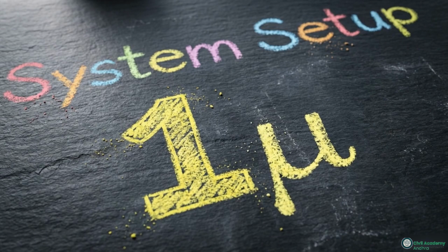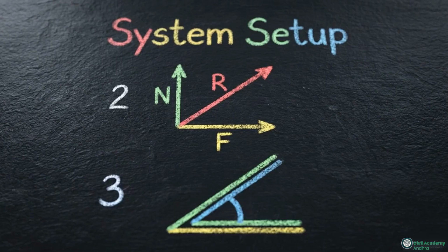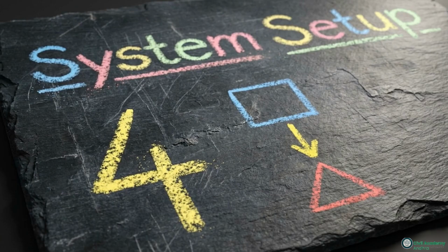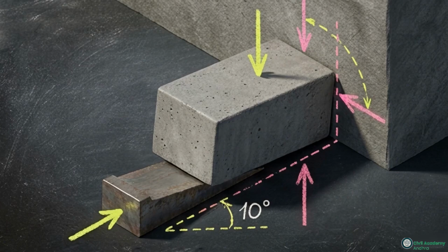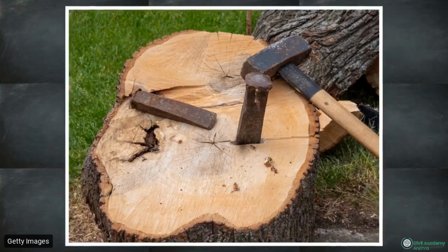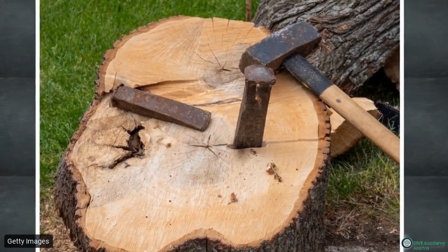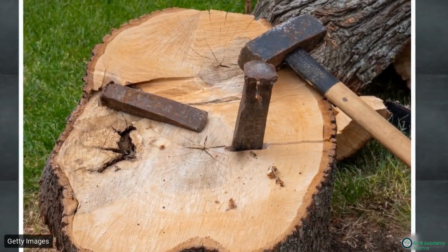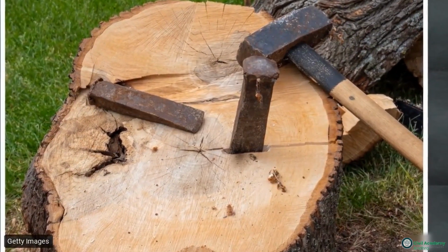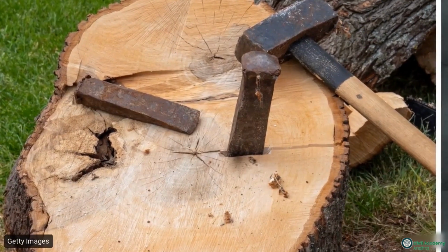This four-step cheat sheet outlines the entire process. First, find your friction angle. Second, merge your standard forces into single resultants. Third, calculate your tilts, adding the wedge angle for the inclined surface. Finally, solve the block first, so you have a known force to bring into the final wedge calculation. Wedge mechanics rely on this systematic reduction of variables. By condensing 6 independent forces into 3 resultants, we reveal the underlying leverage of the machine.